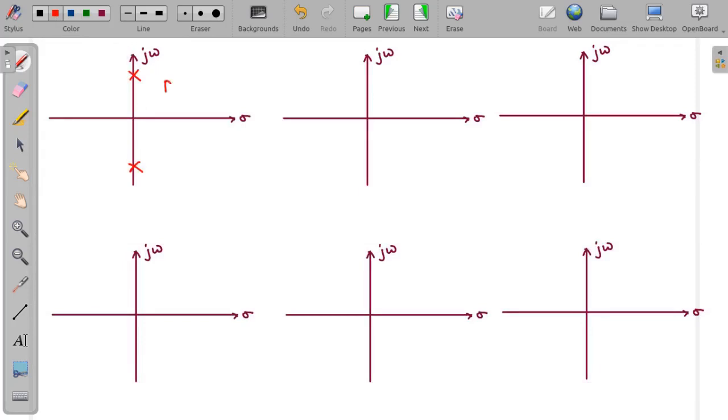So over here we have a single row of 0, row of 0 is equal to 1. Now over here we can also have poles like this. Over here also the number of rows of 0 is equal to 1, but here your auxiliary equation might look like this: s to the power 4 plus 4s square plus 3. Okay, so at that time you will have multiple poles at different locations on the j omega axis.